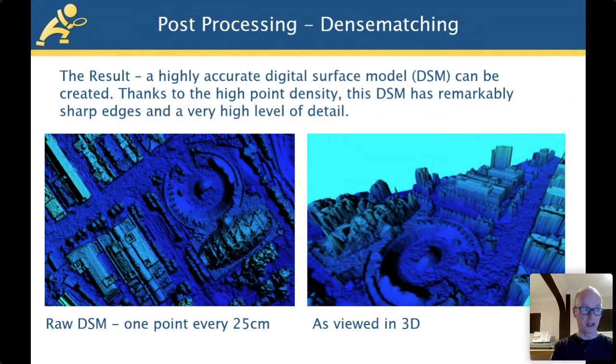This is directly derived from photography. So this again is another product you can spin off straight from your photography, and it's a hugely useful data set for things like measuring building heights, tree heights, line of sight, position of mobile phone masts. All these sort of applications are used in conjunction with the color information from the photography.